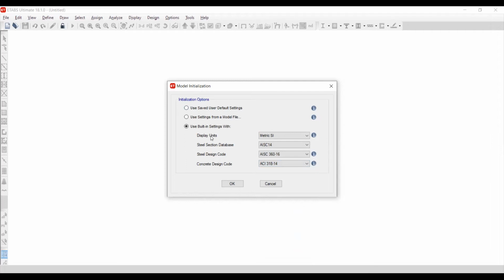So, initializing the model is based on the project that you have. Okay, I have the project, I use the metric, no problem. Is the project steel or concrete? Ask yourself. If it's steel, what sections does the country have in the database? What type of sections and materials do they use? You can select what code you are following, what standard requirement.